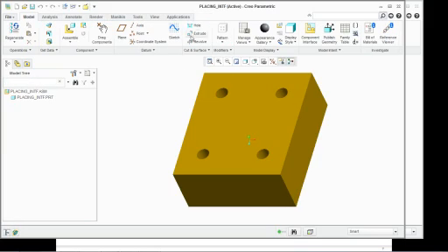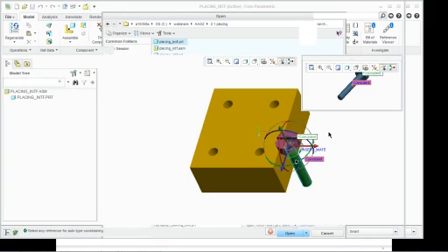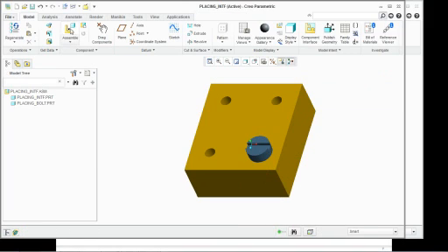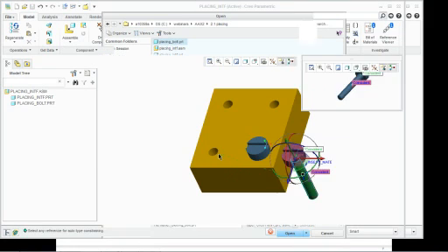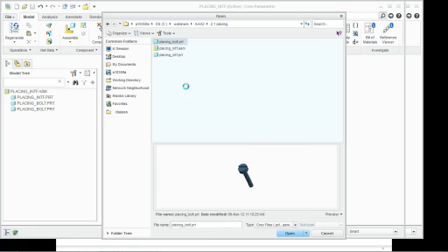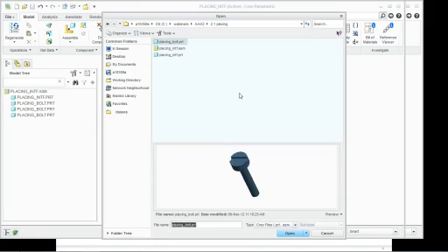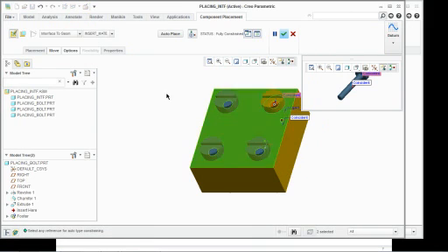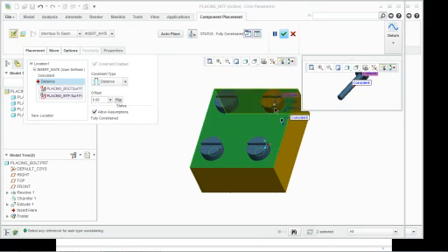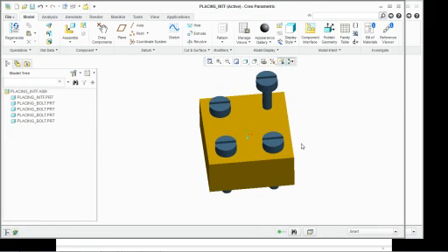So if I go to my placing interface here, I'm going to assemble, I'm going to pick my placing bolt. Then notice it already pre-selected that surface there, so I can pick there and pick there. Insert it again, placing bolt. I just pick the bore and the surface. Again, placing bolt, we'll pick the bore, the surface. And you may say, well, maybe I don't always want to do it that way. I want to offset it once off of here, so pick the surface, and then I can go back in and edit it, just like change it from a coincident to a distance.